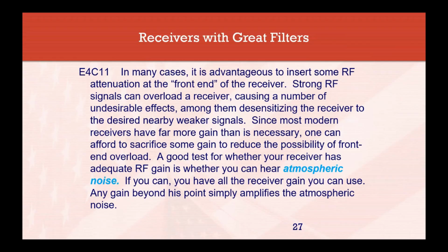Good test of whether it has adequate gain: if you can hear atmospheric noise in it when it's on, then you know that you've got some pretty good gain. Now, my Yaesu radio that I use all the time has two attenuators, a 1 and a 2, and I can attenuate the level coming in. It also has two preamplifiers, amp 1 and amp 2, so I can get additional amplification. So you can kind of juggle those things so that you get the best sensitivity and the best quality signal, especially when you're juggling around strong signals that are getting in the way that you don't want.